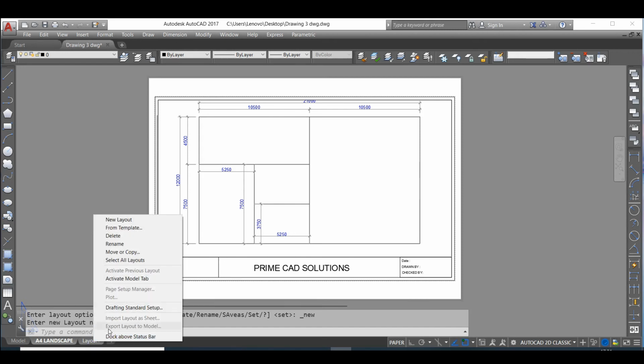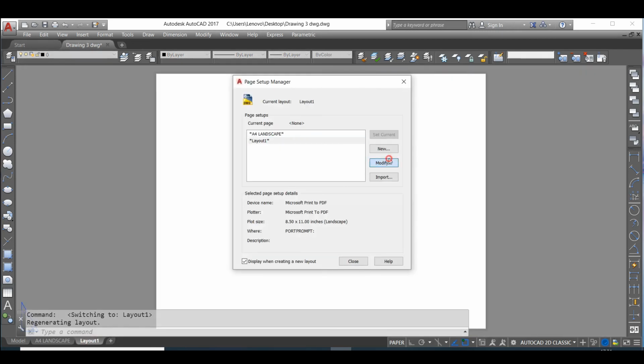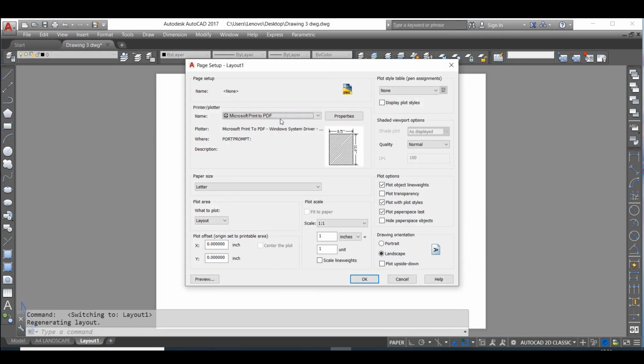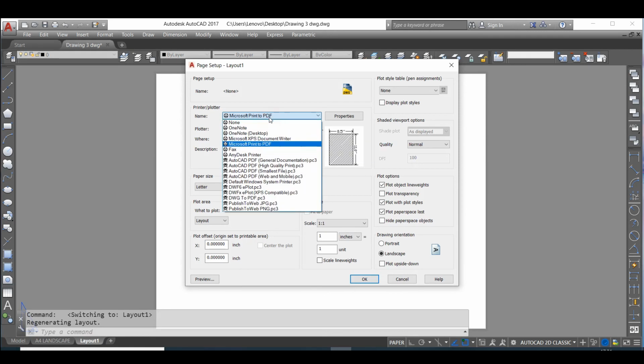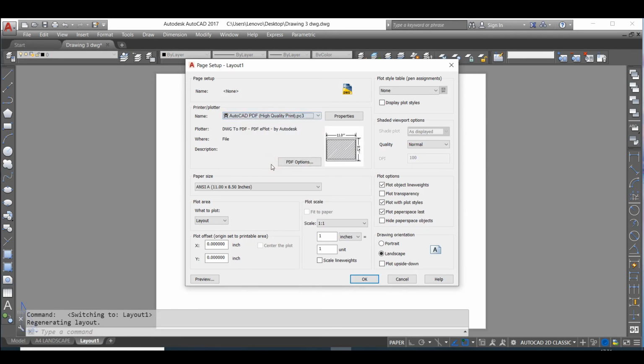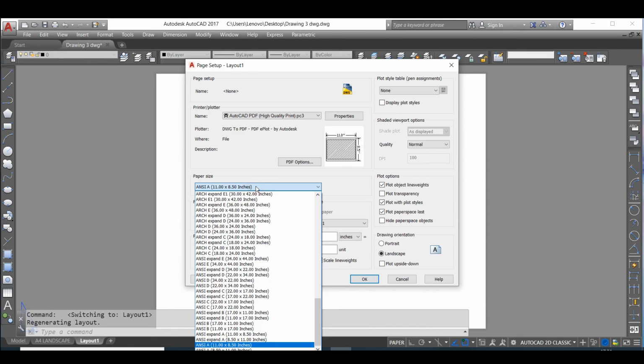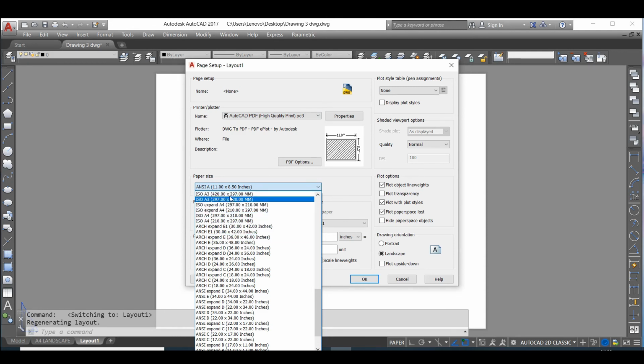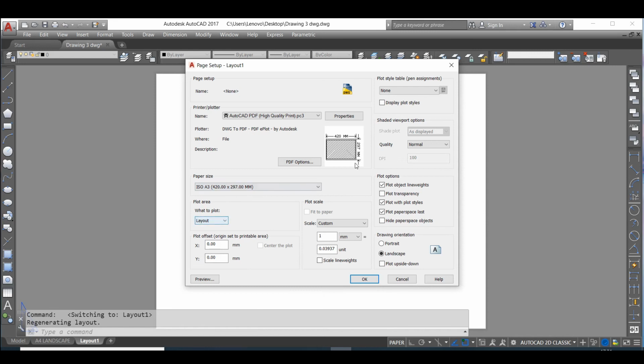I make this layout A3 layout. So I modify this one. The same inputs we gave earlier, no? The same inputs we give in the A3 also. I move fast. A3, ISO A3 landscape. Now you see the dimension will change into A3 paper size.